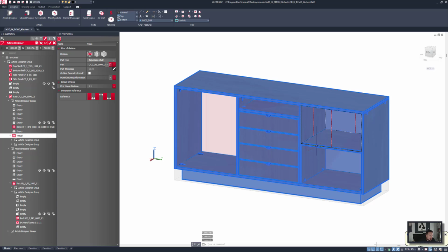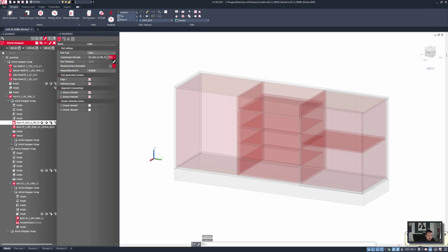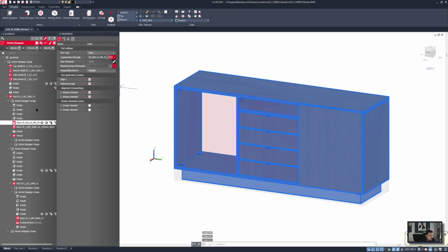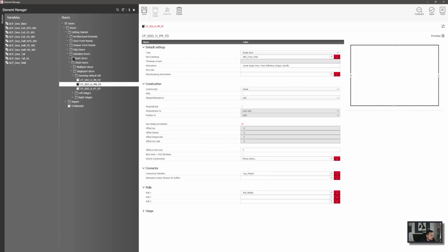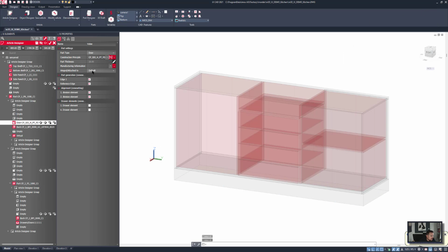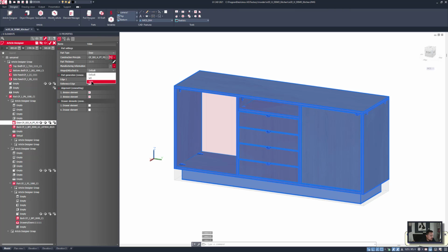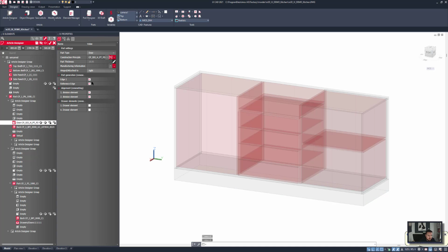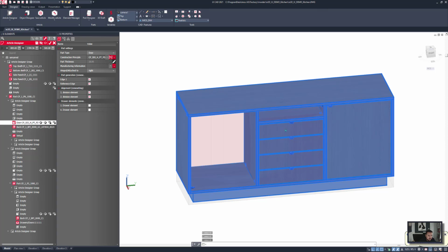And again, we'll just use linear division in here, and then we want a door. And this door in here, I'm going to change to be an inset door to match my inset drawers. So let's go to inset, single part, and in here I want to pull top. And I'll say that this should be hinged on the right hand side. Okay, this is looking a lot better.